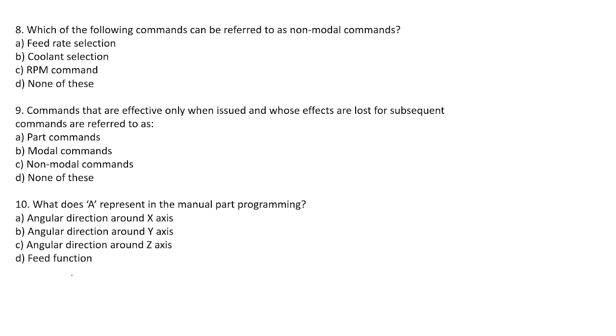It's like you have selected coolant on. Coolant on is M08, and coolant off is M09. If you don't key in M09 in the program, it continues to have coolant on. This is known as modal.